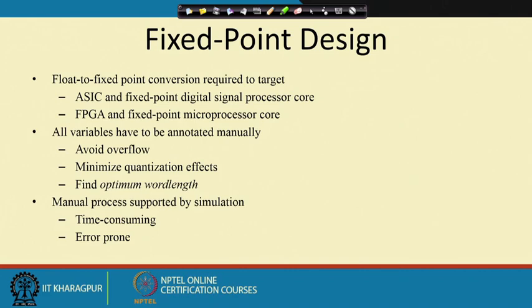If the result value is more than 511, at that time what will happen? I lose the data. So 512 will be represented as 0, though the original value of the data is 512.